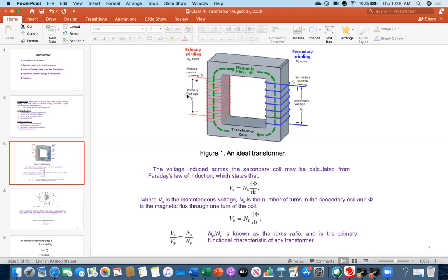Now, if you apply DC voltage, everybody look seriously. If you apply DC voltage, the same thing will happen. There will be flux, and this flux will go, but that flux will be constant flux. It is not time varying flux. This means once this flux comes here, it will interact with this coil. This coil is static, it is just placed, it is not rotating.